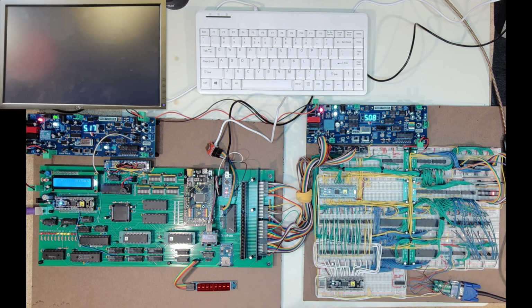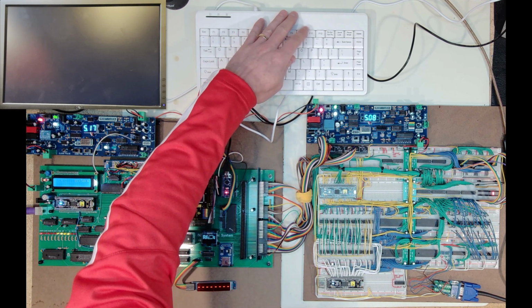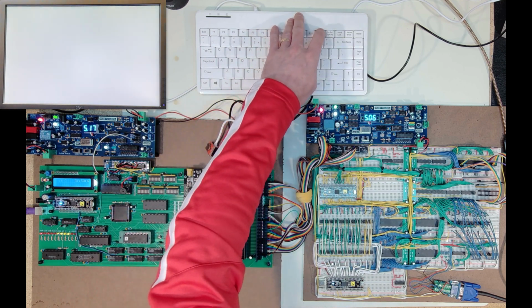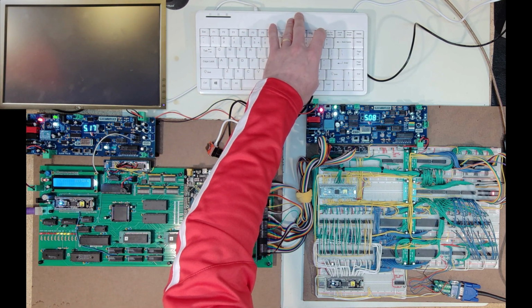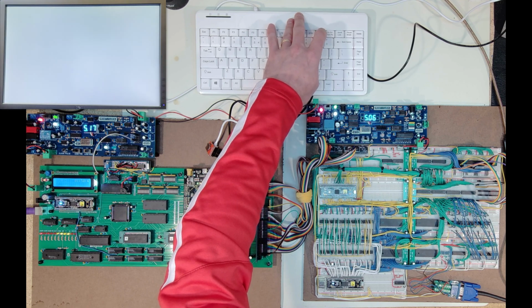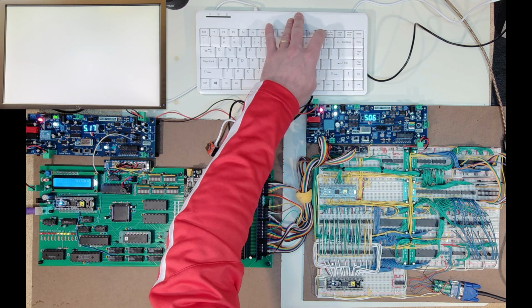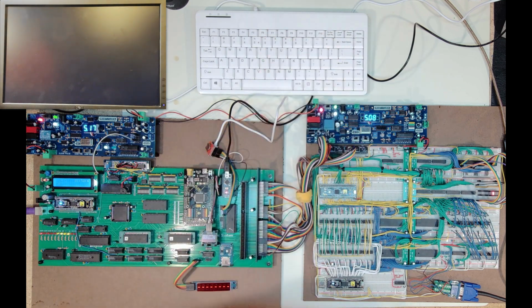But with all of this, I was actually surprised on fire up. It pretty much was where I needed, minus I had to add those two transceivers for the low byte, high byte. I had kind of overlooked that, and so I came back in and quickly added those in. But so far, this appears to be working fine, and I'm not worried about that noise, because I think that's just the nature of a breadboard running a 25 megahertz pixel clock on it. But this is working, and I'm quite happy with that result.